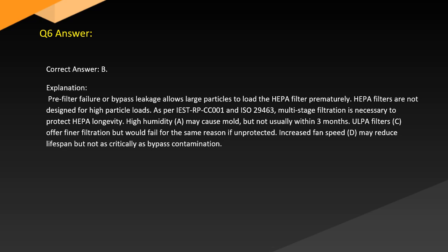High humidity (A) may cause mold, but not usually within 3 months. ULPA filters (C) offer finer filtration but would fail for the same reason if unprotected. Increased fan speed (D) may reduce lifespan but not as critically as bypass contamination.